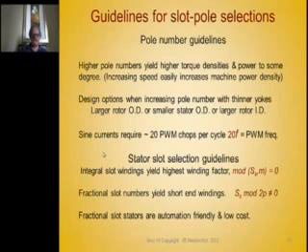Multiple slot coil spans, which are required for integral slot windings, require very expensive insertion equipment. It's standard induction equipment, and there's a lot of it around, but if you're starting out with a new motor design, you don't have that equipment. With these integral slot windings with multiple tooth coil spans, you either have to hand insert the coils, which is labor intensive, or you have to use very expensive automation equipment.